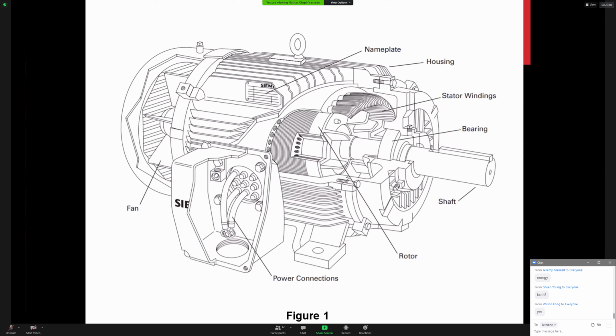If I subject a piece of metal to a rotating magnetic field, it heats up. And it heats up because we have an induction taking place in those metal bearings. It induces a voltage, which causes a current to flow. And that current, of course, is called eddy current. So our eddy currents flow in the bearings.